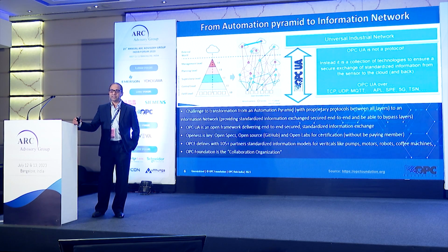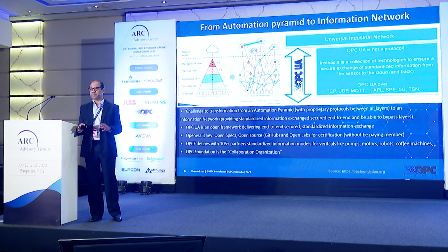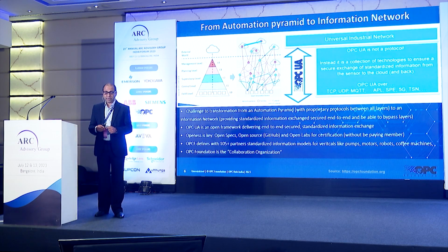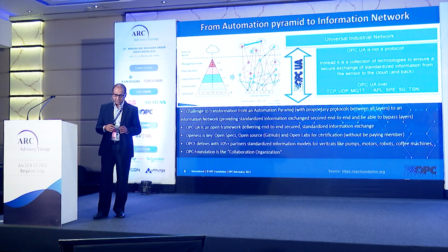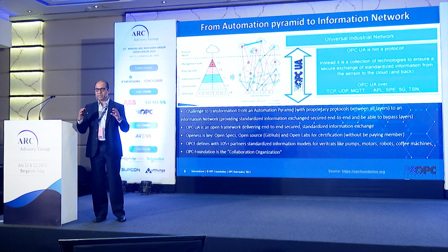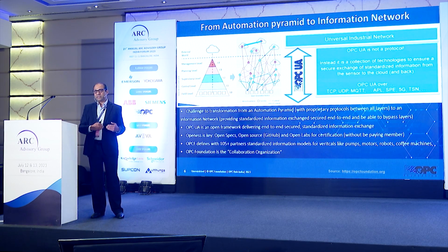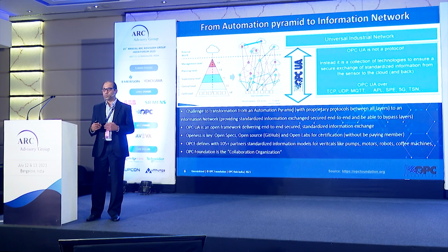What OPC UA has done is break this down into an industrial network. Anybody on the network can speak to anyone else, and everybody knows and understands each other. That's how it is now. I would also like to tell you, OPC UA is not a protocol. It's a communication technology that has been devised to scale from field to cloud and even beyond. And the security is built into OPC UA. OPC UA supports several mechanisms of communication. There is client server, there is PubSub for cloud, and where determinism is required, there is time-sensitive networking too.